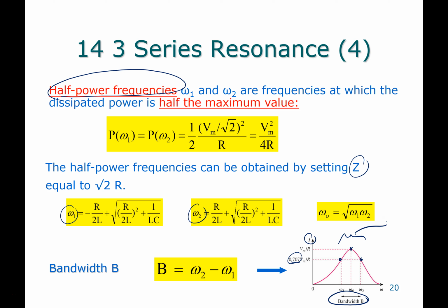Again, if you are designing an equalizer, maybe you want to emphasize your bass frequencies. You get these cars that have these giant bass amplifiers that provide mini earthquakes when they drive by, right? So they've chosen the omega 0 to be like 100 hertz, these really low rumbling frequencies, and you choose the bandwidth to be whatever you want. If you want to just emphasize the low frequencies, you can make it really tight, or you can make it broader if you want to include more. And then you amplify the heck out of it, right?